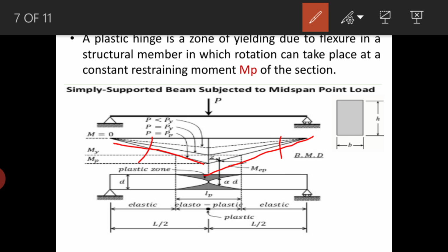Hence the plastic hinges form first at the section subjected to greatest deformation or curvature. So this is about the plastic hinge formation, how the plastic hinge will form, and this classifies next the sections that I explained, that is plastic, compact and semi-compact. If you understand this concept, you can easily understand the classification of sections. I hope you understood this one.